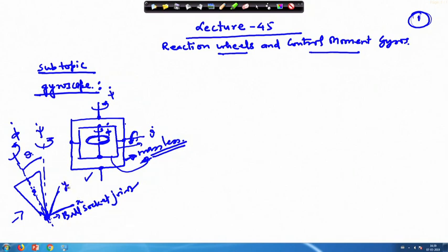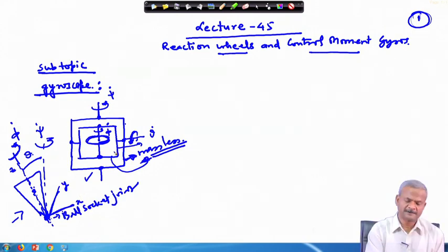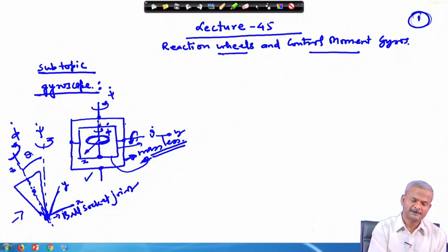We write here x, y, and this is the z axis, and we know that this is spinning on this axis as shown by this arrow. But as in the gyroscope we discussed last time, this x axis, the y axis going in this direction, and the small z axis are not spinning along with the disc. Similarly, here the x and y are not spinning along with it, but are nutating, and this axis is also precessing, and this is because of the symmetry.